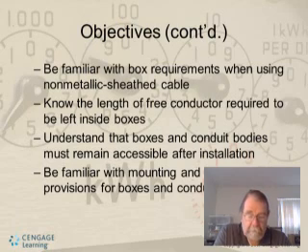Again, we're doing the objectives, what you should be able to do after this unit. You're also going to need to be familiar with the box requirements when using non-metallic sheathed cable. Know the length of free conductor required to be left inside the boxes. Understand that the boxes and conduit bodies must remain accessible after installation, and be familiar with mounting and supporting provisions for boxes and conduit bodies.